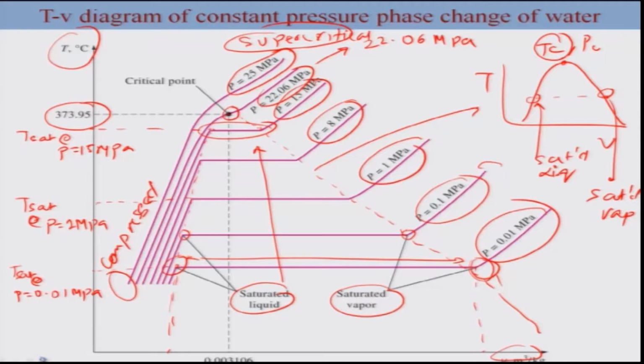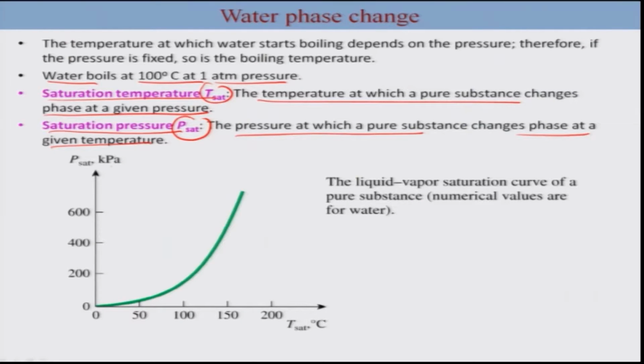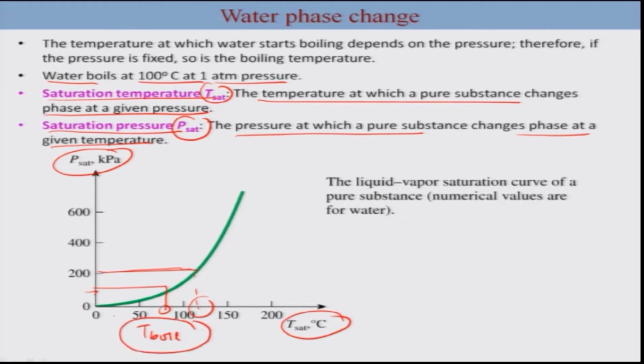Okay. So, based on this analysis you can clearly understand that the pressure as a function of T sat should look like this, and this is the reason that if you reduce the pressure, the temperature will be lower. So, if you reduce the pressure from 100 to somewhere here, the corresponding temperature will be less. It will not be 100 degrees Celsius for the case of water, as in the mountains. If you fix the pressure, this will be the temperature at which it will boil. The boiling temperature reduces, okay, and that is what we see when you go to the mountains and start heating up.